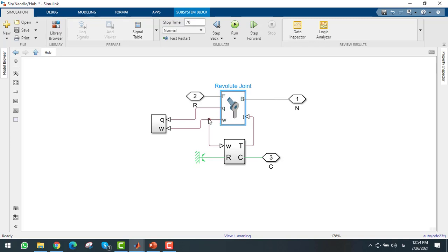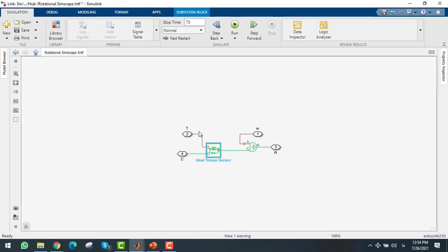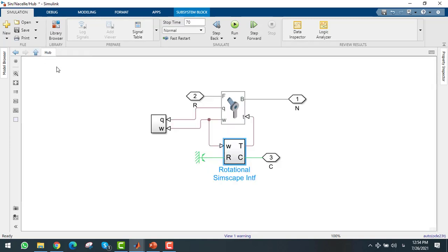The angular velocity of the rotor comes into this block, which produces a torque, and then this torque feeds into the joint and becomes the motion of the hub, which fundamentally rotates the blades. So this is an inverse dynamics kind of loop, which we can see here. We get the angular velocity, so the kinematics, and then we find the joint torques of the revolute joint.